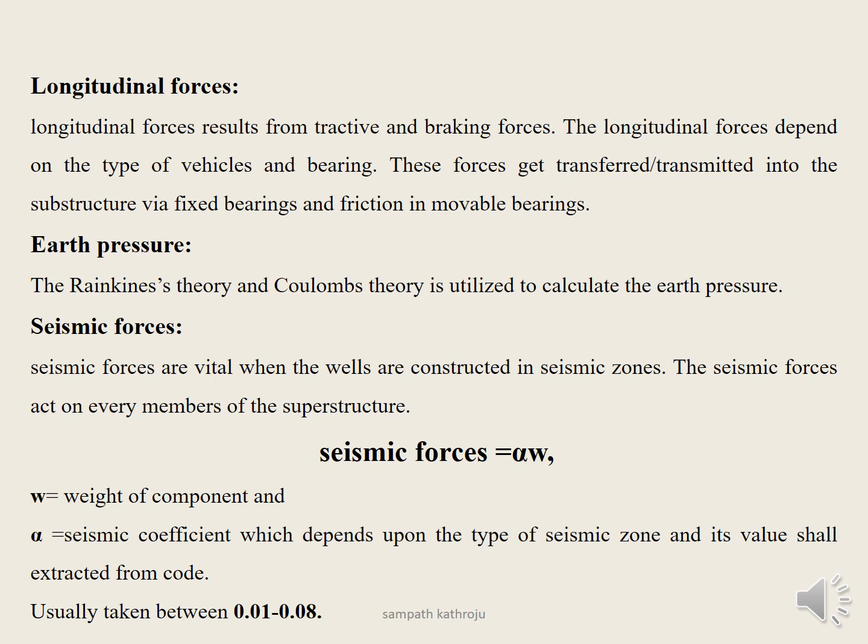Then come the seismic forces, which act on every member of the superstructure. In the case of earthquake, the force is alpha into W, where W is the weight of the component on which the seismic force is required. Alpha is the seismic coefficient depending upon the type of seismic zone, and its value is taken from 0.01 to 0.08.